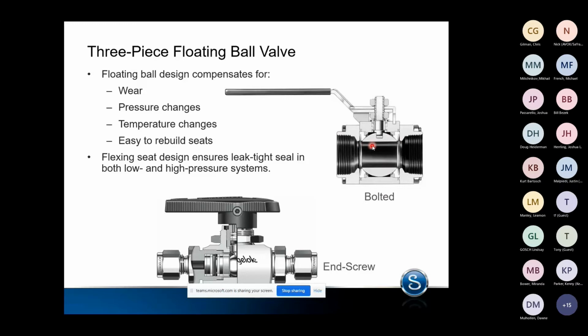Ball valves inherently have a limited shelf life or function life. You've got a highly precision manufactured stainless steel ball that's making a seal against a much softer, high performing plastic. Could be a Teflon, could be a PEEK. Stainless is always harder than this plastic. And over time, in order to maintain the seal, you've got a pretty tight contact surface. This little knife edge that we've created over time is going to start wearing against that seat, and you're going to have to replace those.